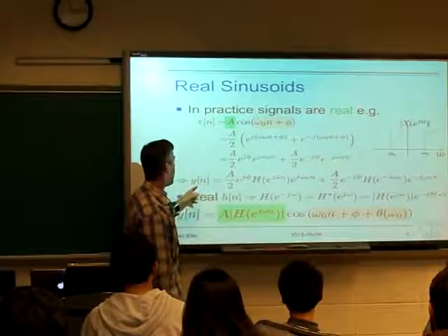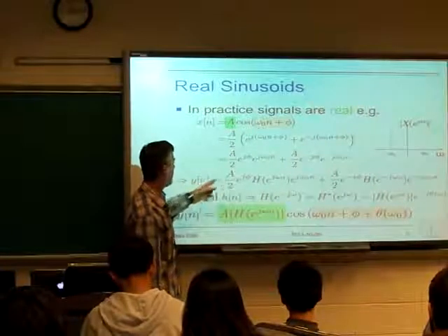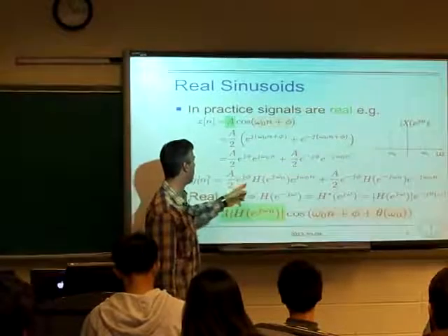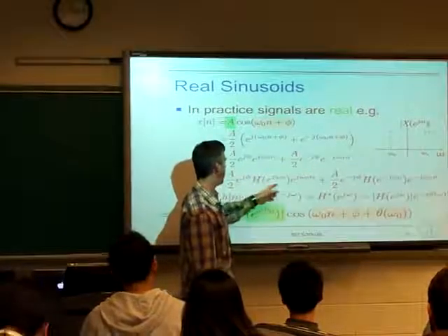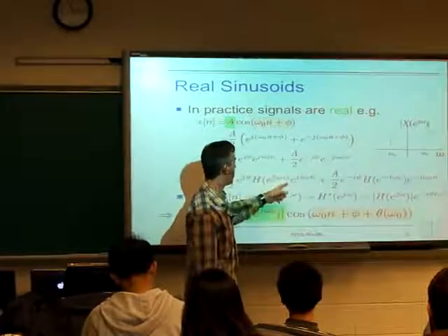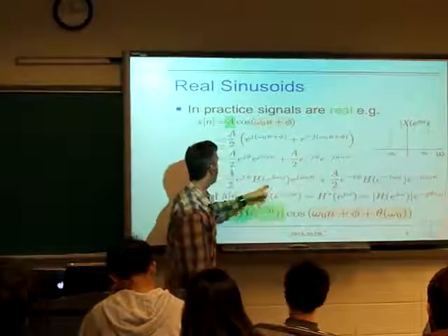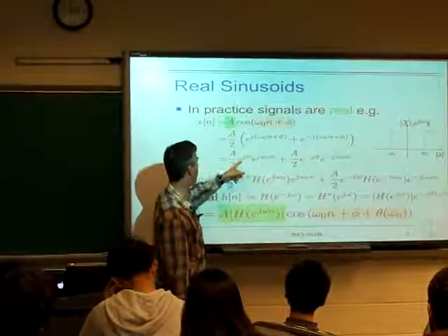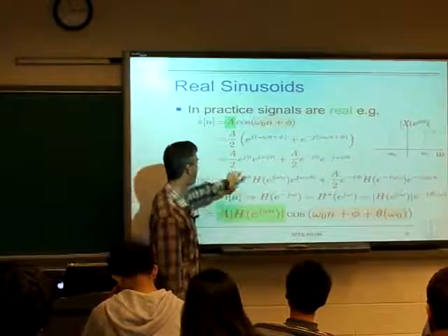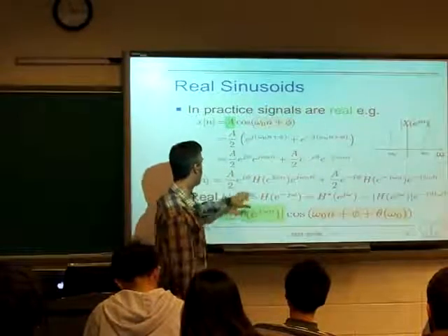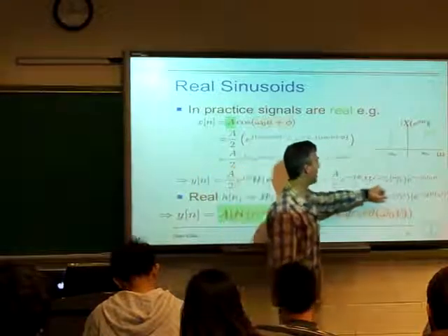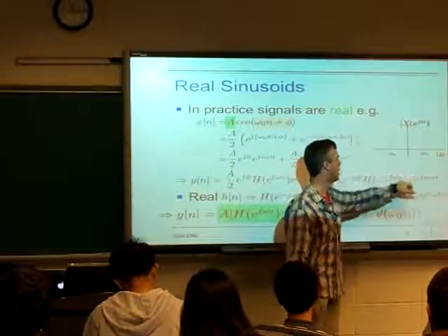Now, we just worked out that if we put in one of these e to the j omega 0 n's, then the output is going to be the value of the DTFT at that omega 0, H of e to the j omega 0, times that e to the j omega 0 n. We've got these extra terms coming out here, the e to the j phi phase shift and the A on 2 scaling, but it's just linear, so that just carries through. So we get this one for the positive frequency component, and this one for the negative frequency component, the minus omega 0 part.